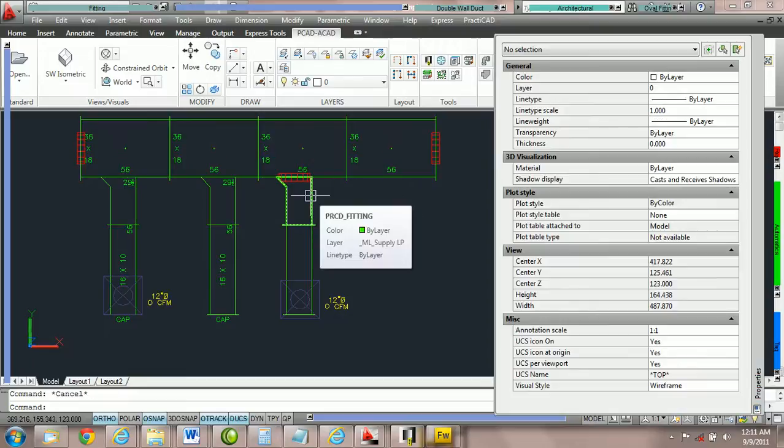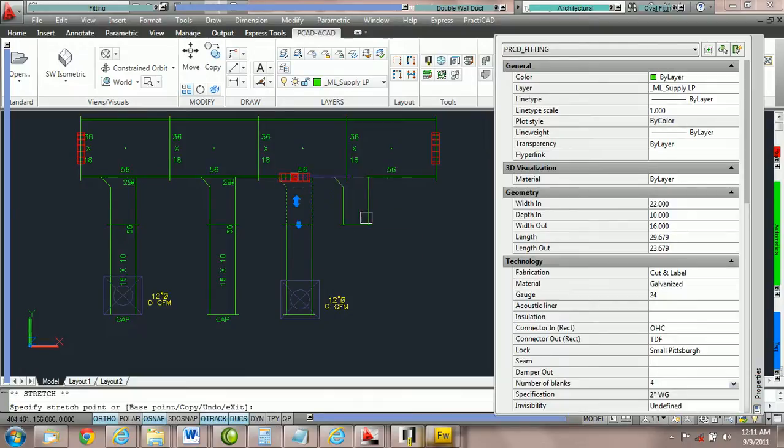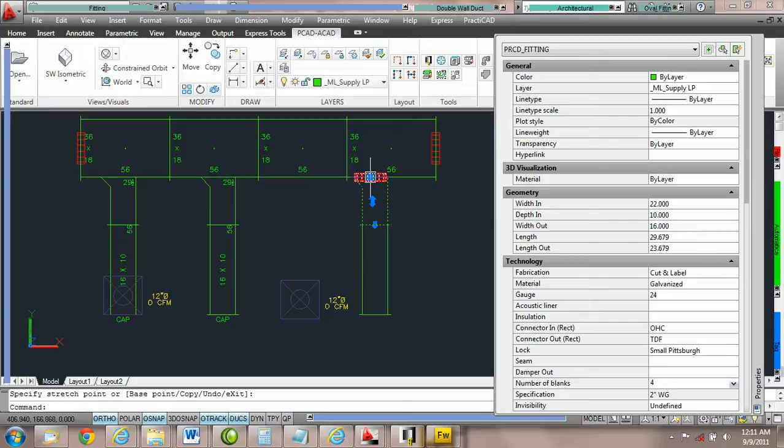However, this one is going to be broken. And once a duct line is pulled off of a main trunk line, it is very difficult to actually reattach it. So please follow the recommended methods for move and copy.